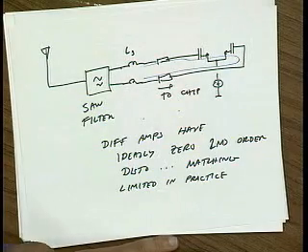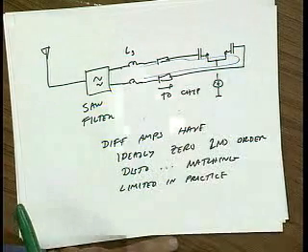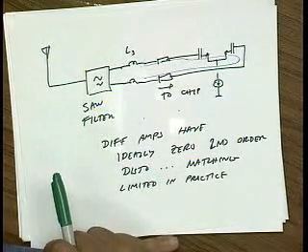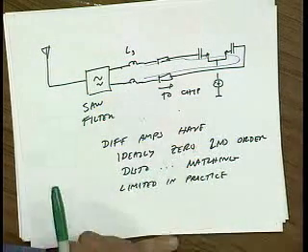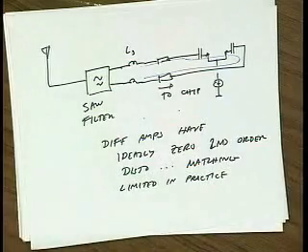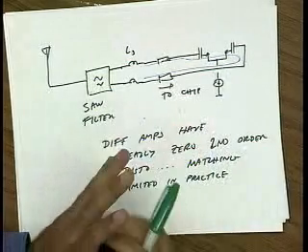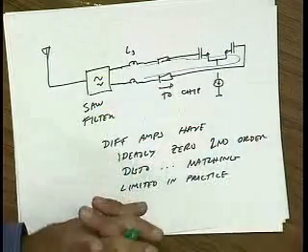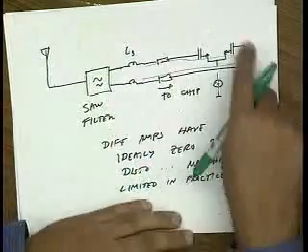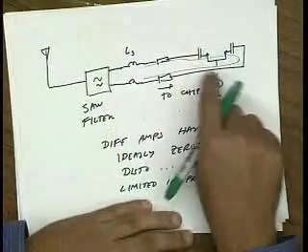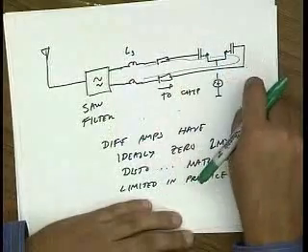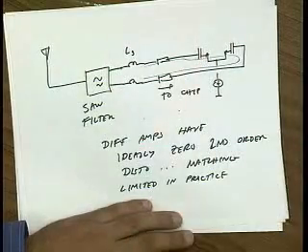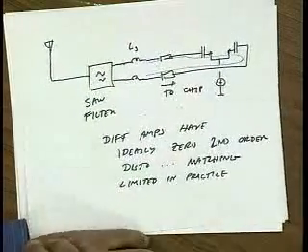And having a good IP2 means that this is very good for direct conversion, right? We haven't talked too much about architecture in this class, but we know a direct conversion receiver is one that takes a signal and converts it down to DC. We've also learned that any even order distortion generates DC. So if this amplifier has even order distortion, it will generate distortion right in band. And by making it differential, effectively we're making that distortion very small. Okay?